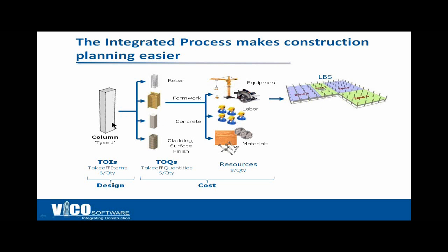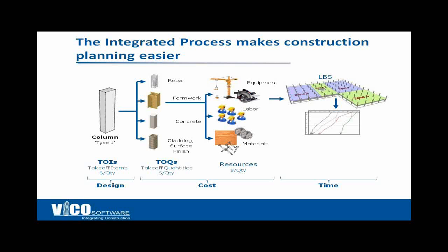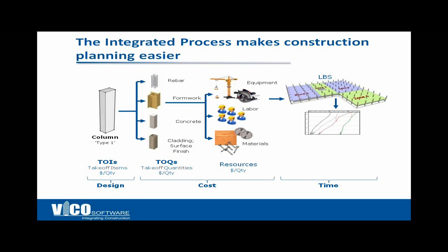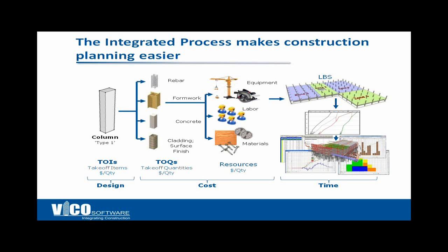Since we have our building in 3D space, our cost assemblies, and our resource information zoned by locations, we can now create a schedule very easily and basically automatically. This is where you would start your baseline schedule, and you would bring your team in to look at it, to analyze how much buffer is needed between tasks and what ways you might be able to make this more effective. You can display it in Gantt chart view if that's more comfortable for people, but the flowline actually tells you a lot more.